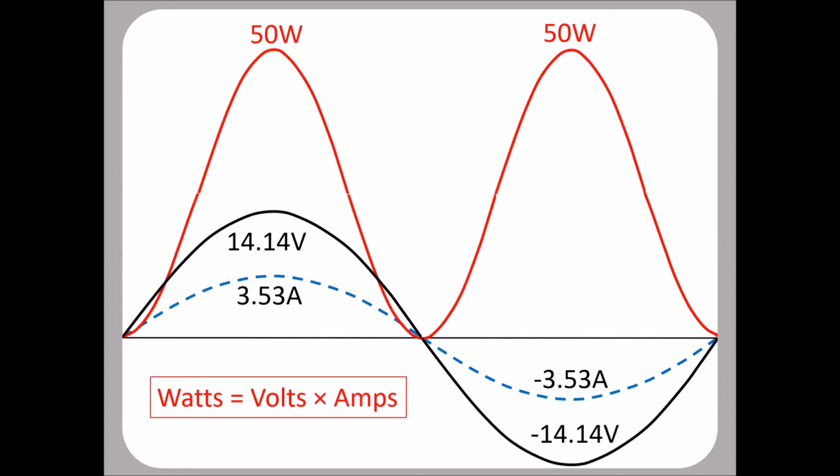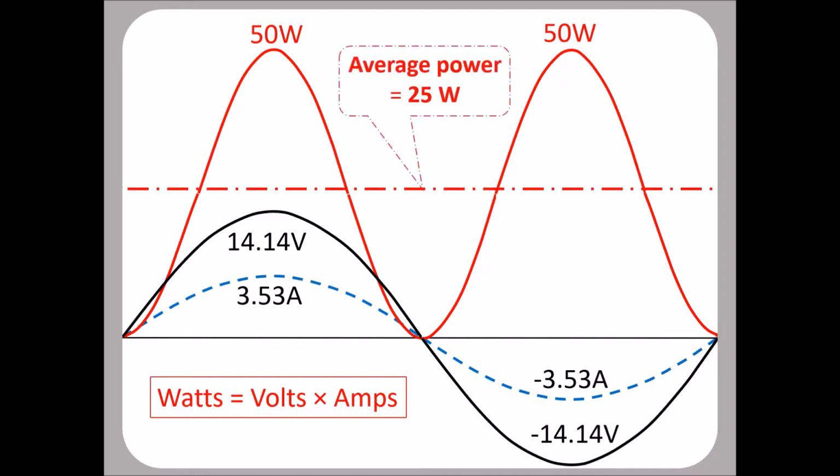Now, it's not much point bringing them up and saying, well, I'm not drawing any current for every 100th of a second, I don't draw any power. You don't need to send me a bill, because they'll turn around and say, yes, we do. You're drawing 50 watts. Obviously, what really matters is what's the average. And in this case, of course, the average power is 25 watts, exactly the same as it was before.